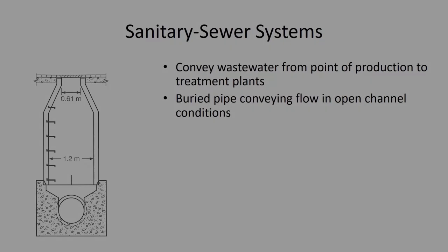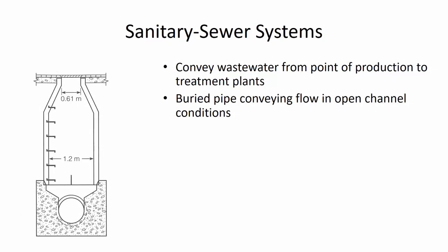So the sanitary sewers and also storm sewers work with the same idea that we're trying to convey wastewater towards some point of treatment or point of disposal. Generally it occurs in buried pipes that are flowing with open channel conditions, which means that even though it's a pipe, we're going to be using Manning's equation.